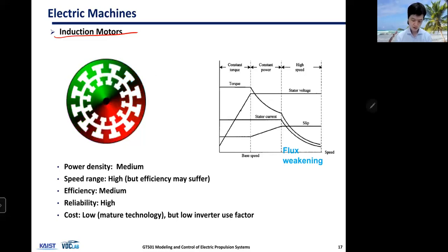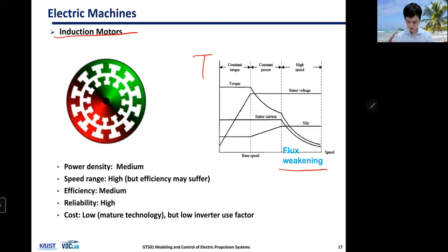So you're looking at the field generated by the stator is rotating, and the rotor is rotating, and as you can see, the field from the rotor perspective is fixed, but from the stator it's rotating. Okay, so you need to rotate the field for the stator continuously along with the rotor, so that you can continue to generate torque. And you are also looking at the motor map here, constant torque, constant power, and then there's flux weakening region.